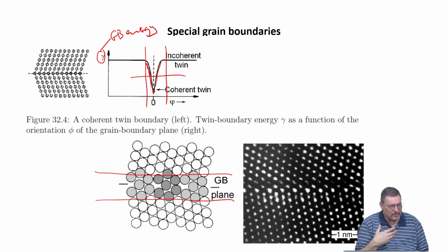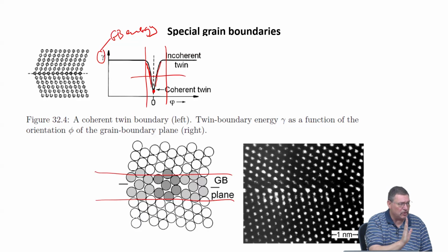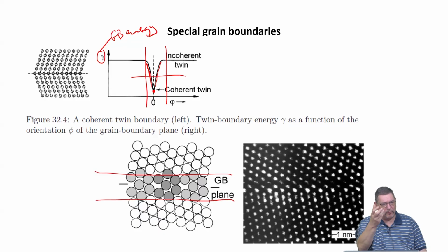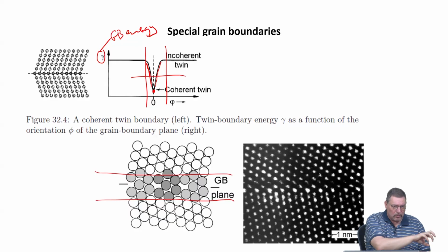And it works because the beauty of the Gibbs approach is that the position where you put this mathematical Gibbs dividing plane can be varied without changing the result. So this means that the Gibbsian description of having a mathematical 2D plane as a boundary between phases, for example, can also be applied to the grain boundaries or to phase boundaries. But if we think of a diffusive process, we really have to go from the continuum description based on Gibbs to the local atomistic description, and then we have a grain boundary zone, a slab of a certain thickness.